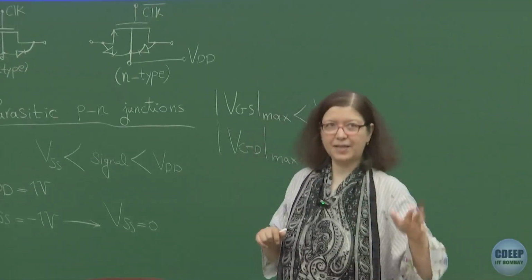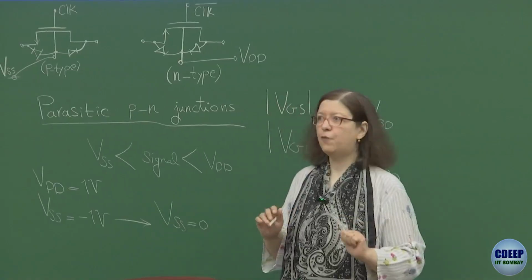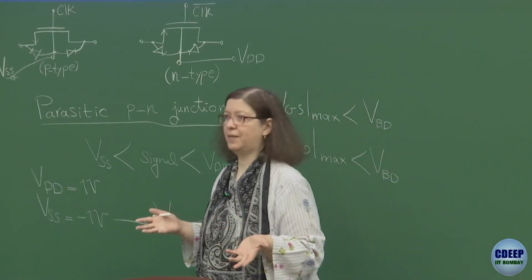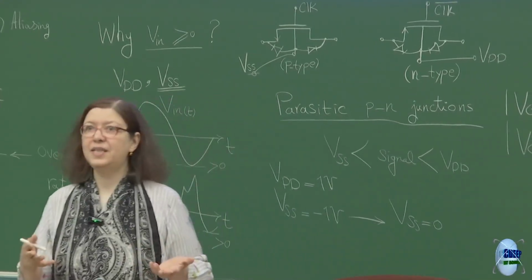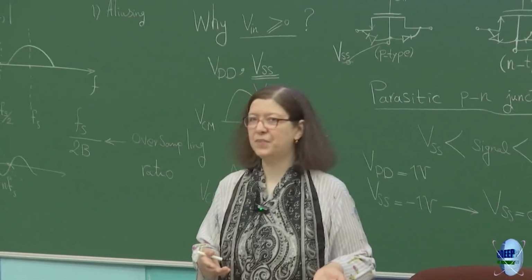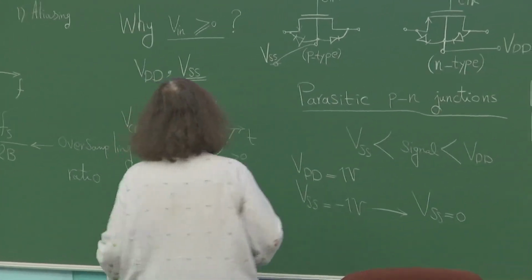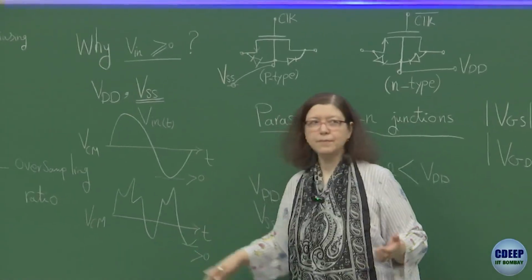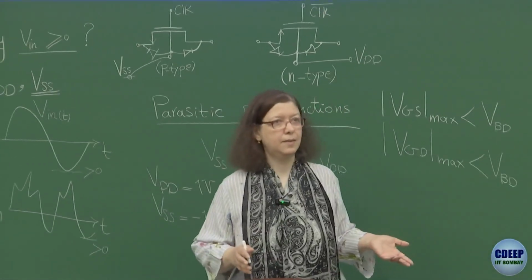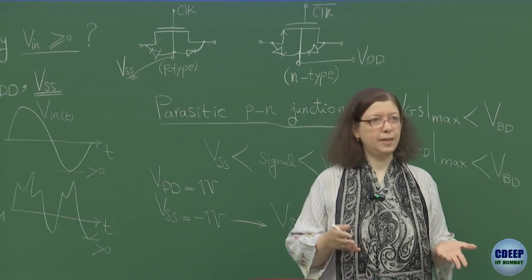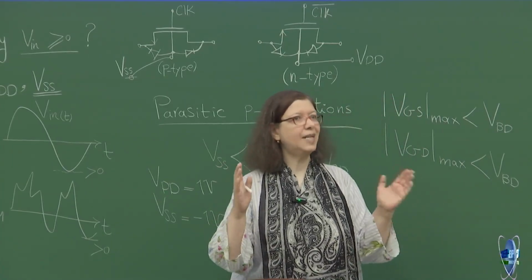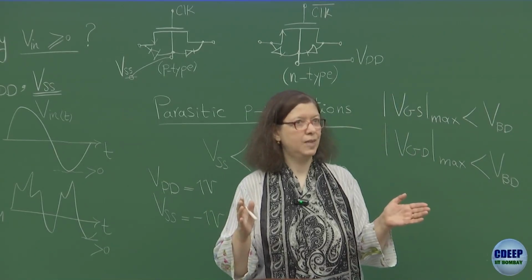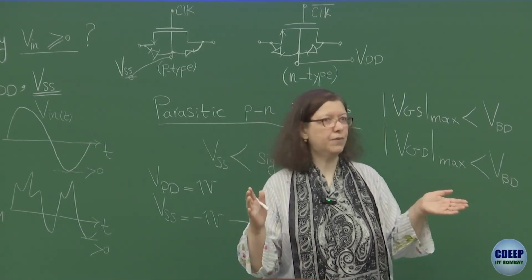So Sanketan asked this question: why do we use only periodic signals for FFT? In fact, FFT and DFT are subject to this assumption. What if we have an arbitrary signal? So the answer is this: we make conceptually a periodic version of that signal because we have only a limited time window for the sampling.